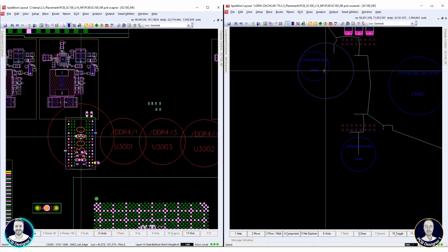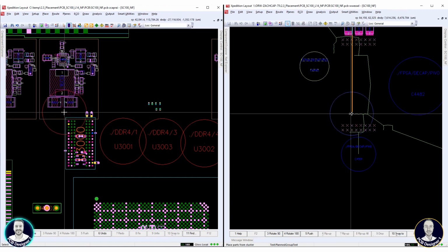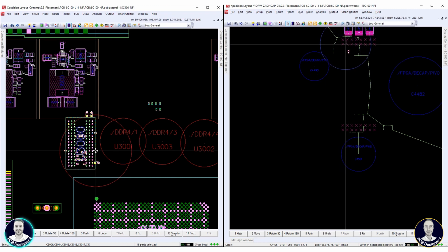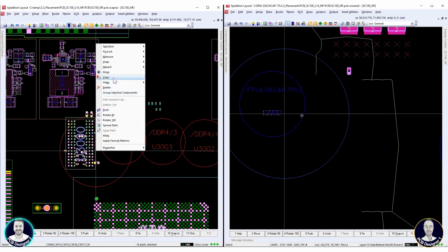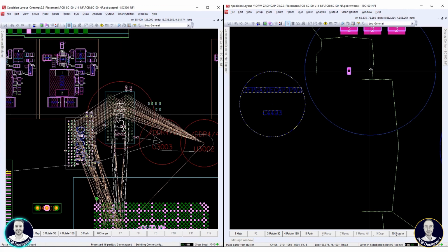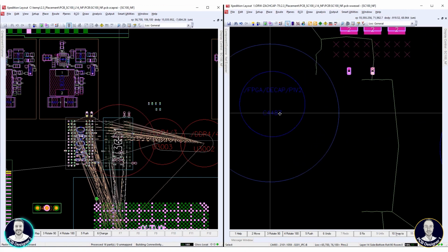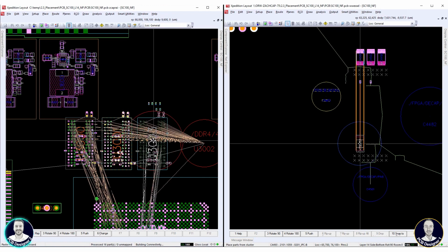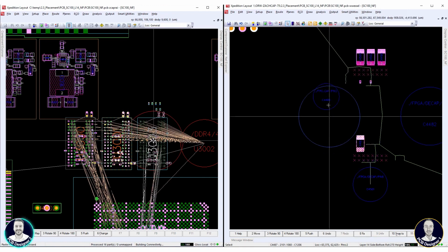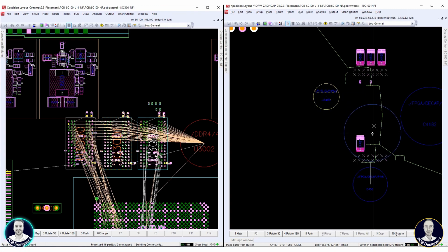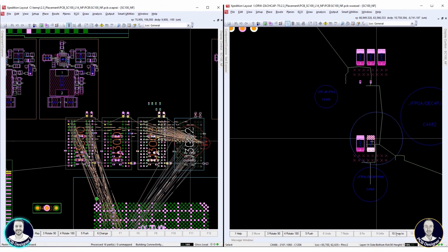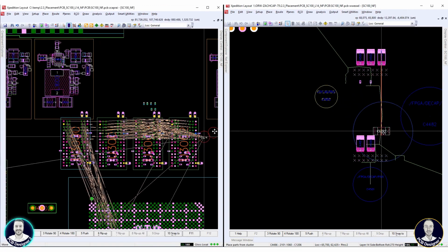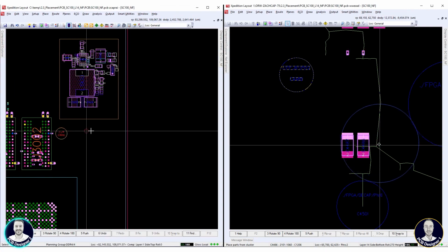So with the VREF components placed and arranged, I can now move on to finishing placement for the remaining 3 DDR chips. I will use the powerful circuit copy command to achieve an identical placement pattern for these last 3 DDR groups. So using the circuit copy command, I can copy the DDR chip as well as all of the decoupling capacitors and paste them down here to finish placement. And finally, we have the termination resistor planning group here that will move off to the side.